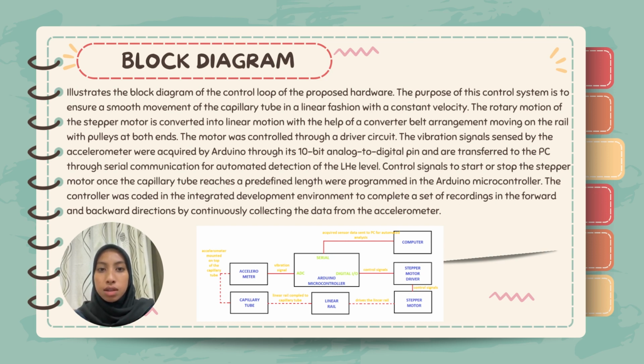The vibration signals sensed by the accelerometer were acquired by Arduino through its 10-bit analog to digital pin and are transferred to the PC through serial communications for automated detection of the LHe level. Control signals to start or stop the stepper motor once the capillary tube reached the predefined length were programmed in the Arduino microcontroller. The controller was coded in the integrated development environment to complete a set of recordings in the forward and back direction by continuously collecting the data from the accelerometer.